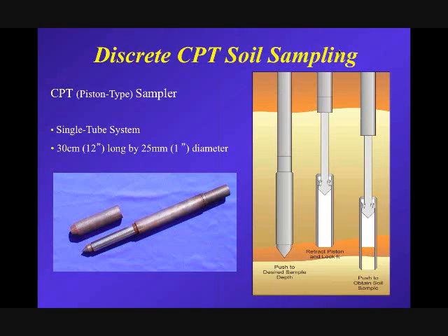So rather than take samples every 1.5 meters or every 5 feet, you now take 1 or 2 samples at discrete intervals based on the soil stratigraphy and the project requirements. So you focus in on the layers that are most important.